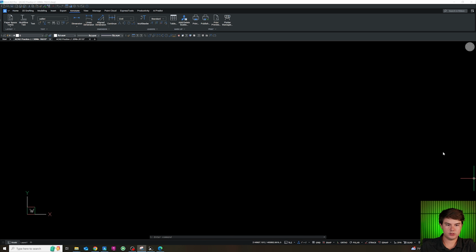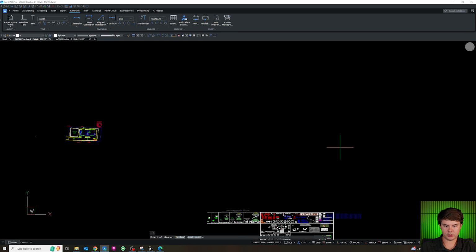And to start this test, we'll draw the property lines. So I'll do L for line, and then at the distance 225.22, less than sign, and then the meets and bounds, 90. And then you'll just do the same thing all the way around.